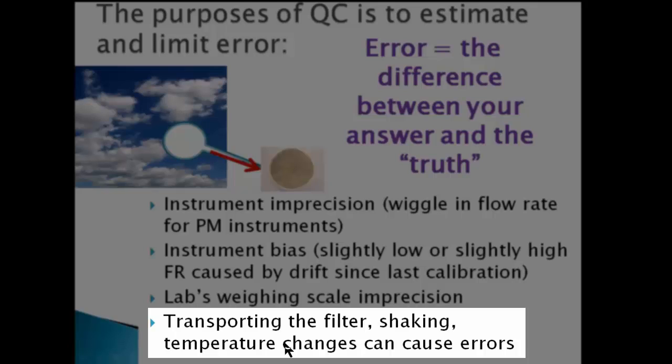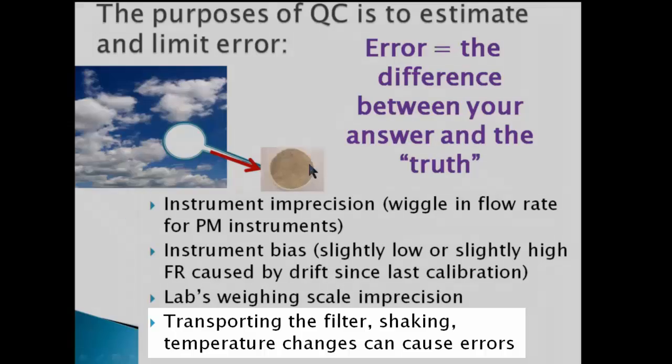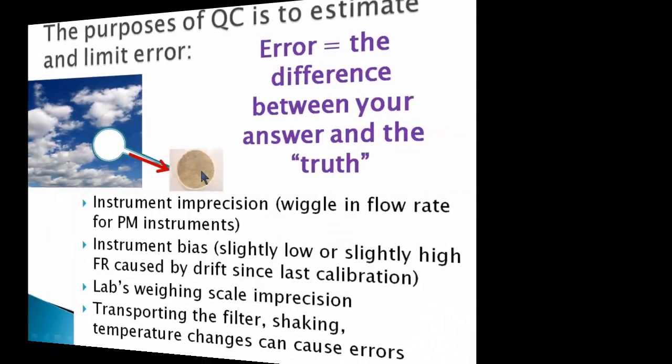Again, remember for PM 2.5, if the temperature gets high inside that cooler, it sits somewhere for a long time and all the blue ice just turns into gel and it gets hot in there. Some of the PM 2.5 on the filter may turn back into a gas, and then when the lab opens it up and weighs it, it's going to weigh less than if that filter had been shipped in a really cold cooler where all the particles stayed on the filter.